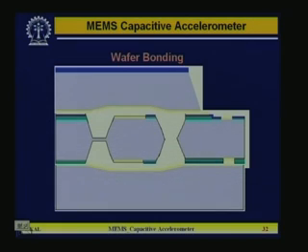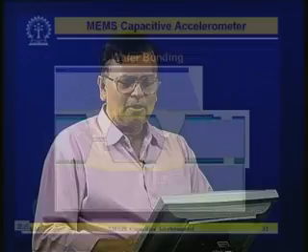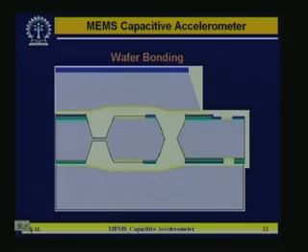Because the C1 and C2 capacitance structure, top and bottom, helps in elimination of any parasitic or noise pickup, since you are working on the differential capacitance, the difference delta C, C1 minus C2, which is proportional to G. That variation with G is what we are interested in. Because there are a lot of conducting planes here, if you use a conducting silicon wafer, it is also going to create a problem, because the conducting wafer with another ground plane will have some parasitics, and that is a major concern in many capacitive accelerometers.